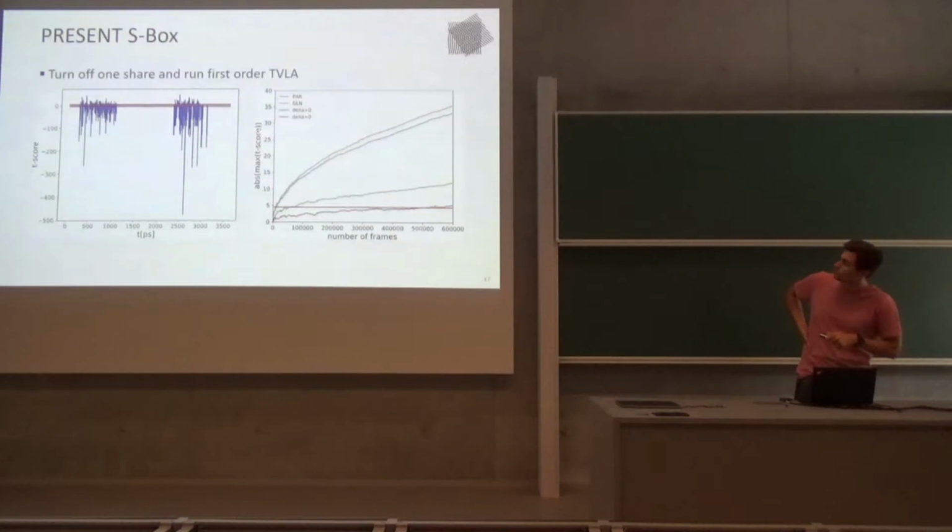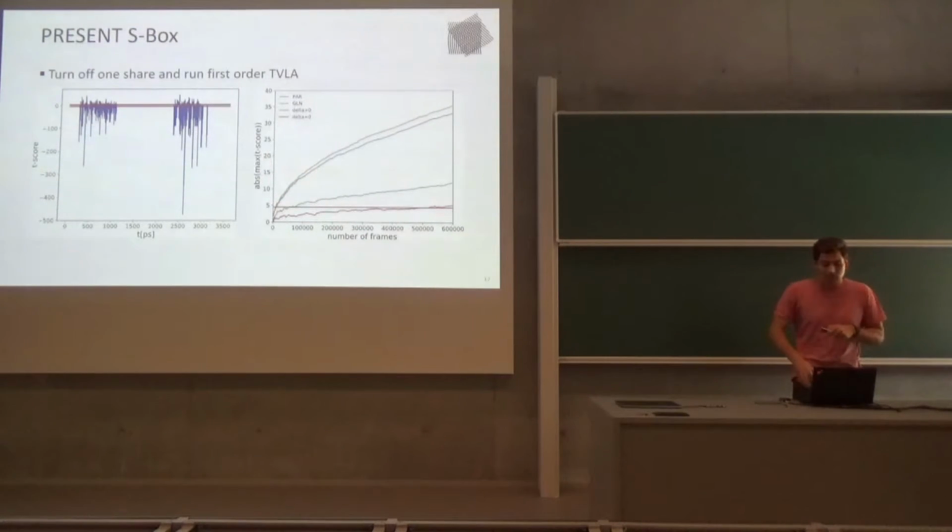So this is just the evolution of the trace. You basically plot the absolute of the maximum of these traces with the increasing number of frames, and you'll see that even using these very simple models in the beginning, you can start detecting leakage. Okay, they're not as good, so maybe you should just go and synthesize your design, but even the simple models can detect leakage. We repeated these experiments with more complex Liberty models and using more complex simulators. Everything holds, but as a simple case, we showcase this.